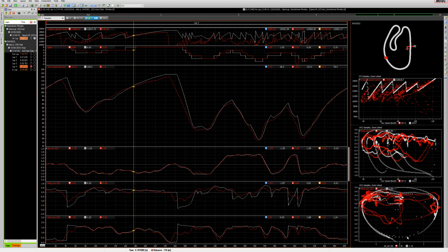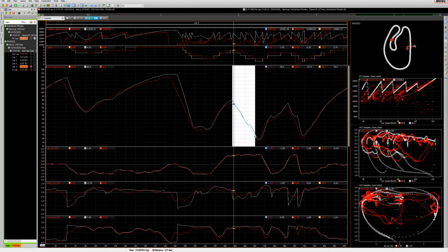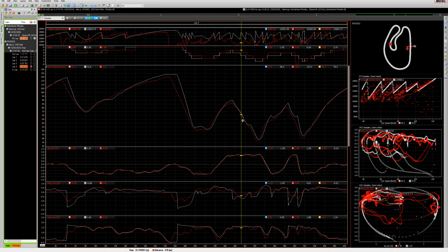Now, due to this increase in braking potential that OpenLAP is actually using, it can brake about 12 meters or 0.4 seconds later. One key thing to note though is the correlation here in the entry of what we call the fig tree turn. This is a case of a turn that is wide in the beginning, and as you go on, it progressively becomes tighter and tighter. And you can see that OpenLAP can actually capture the performance of the kart in this region in a pretty good way.